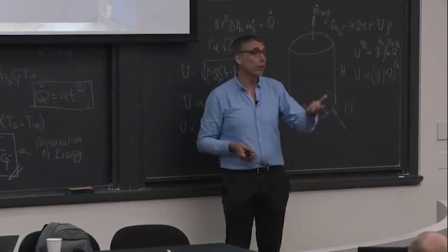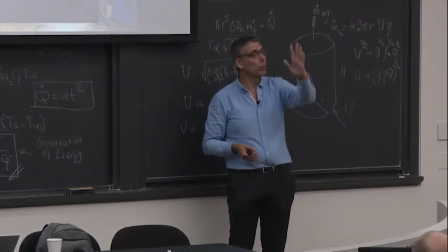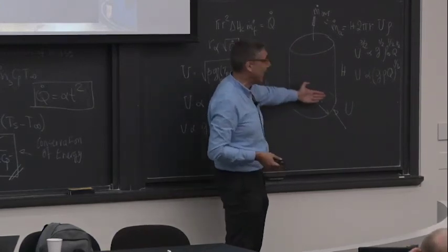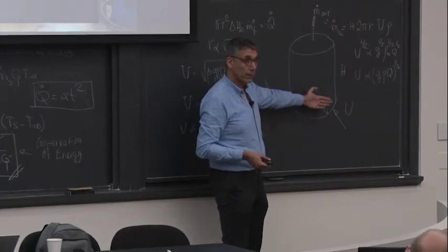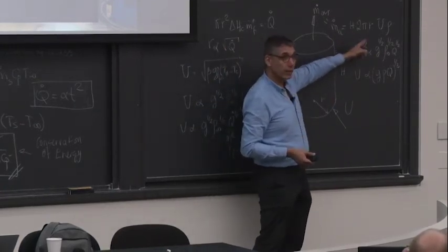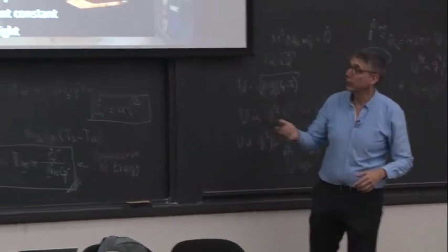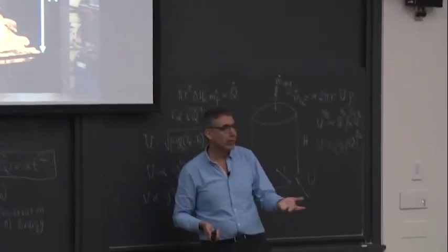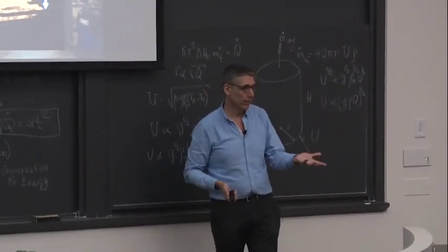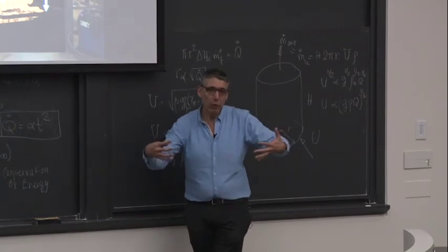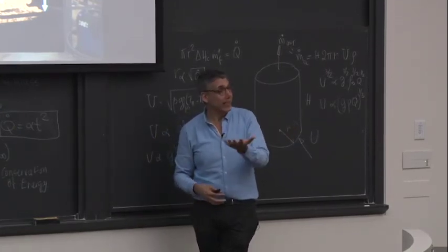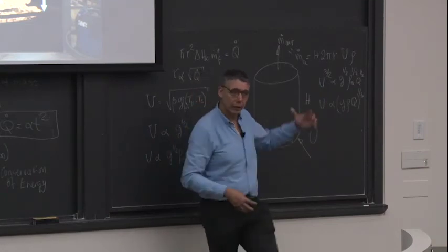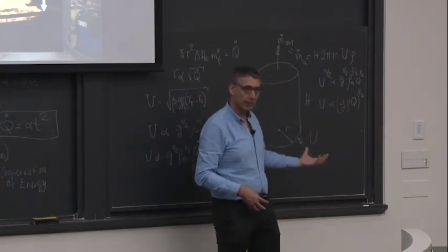So for example, if I'm going to be looking at the entrainment of a spill plume coming out from a window, then effectively I have only half the cylinder. So instead of having 2, I will have 1, and probably my entrainment coefficient will actually be 0.1. It happened to be, instead of 0.1, 0.089. Okay? Because you're obviously deforming the flow a little bit. But you can see how you can play with the entrainment coefficient as a function of understanding how the scaling was done.